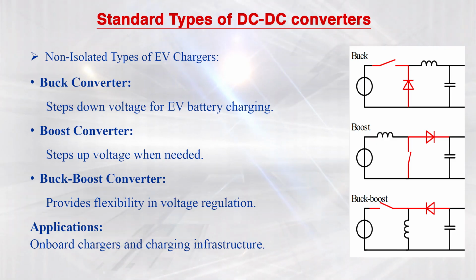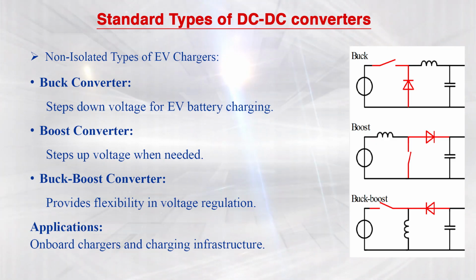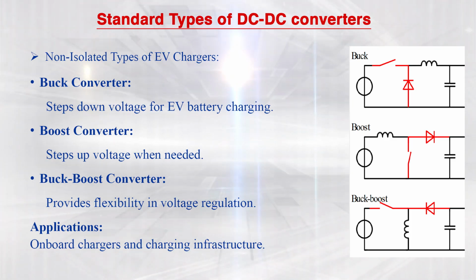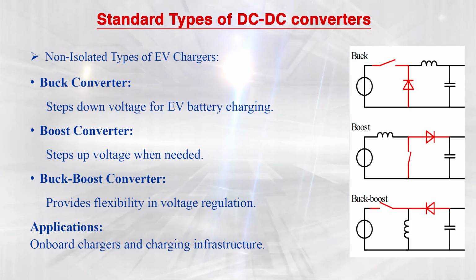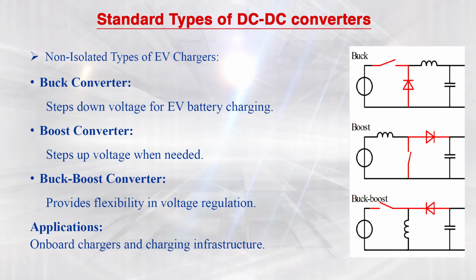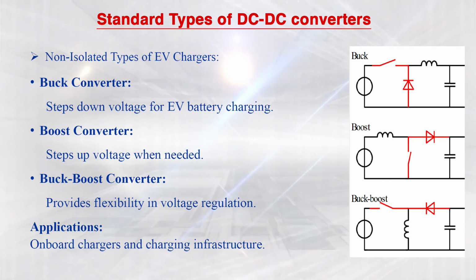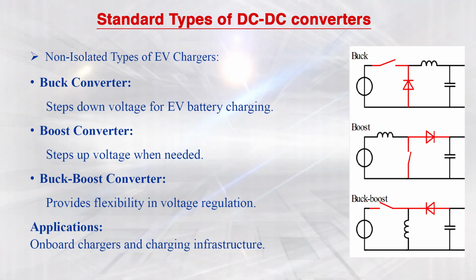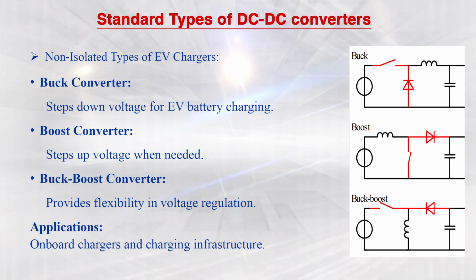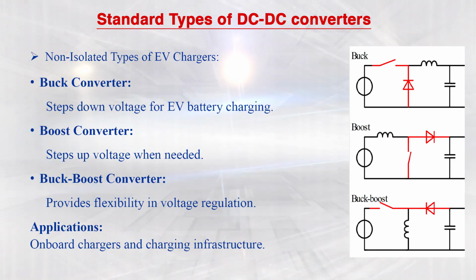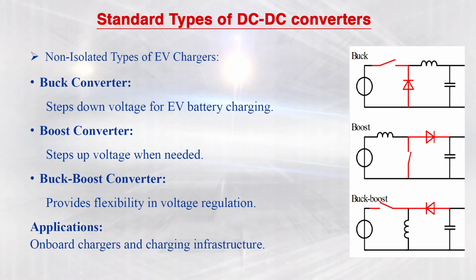Similarly, for single phase application, suppose we have utilized a single phase front end converter for the AC to DC conversion unit. The single phase source is available in India as a 230 volt, 50 hertz supply. This 230 volt will be converted into 325 or 310 volt.